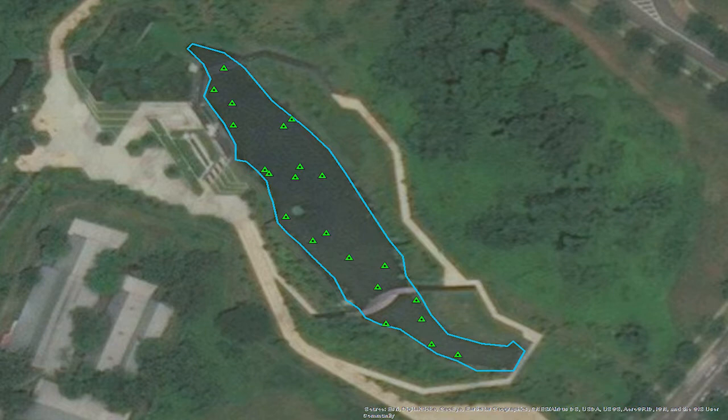In this design, each point in the pond has equal chance of being selected, which is good because we do not want to bias our sampling, and therefore we may have a nice random distribution of sample points. However, with this design, as we see in this map, it also is possible that all sample locations are clustered in one area, which would not be representative of the entire pond.